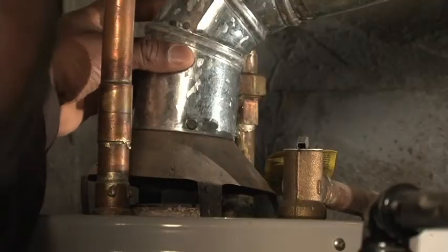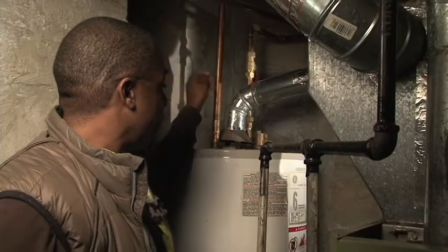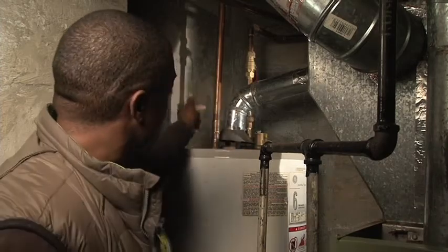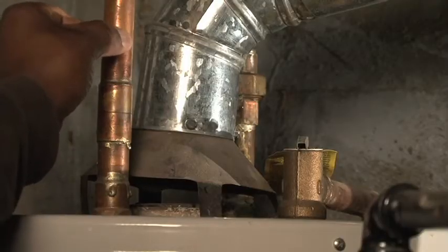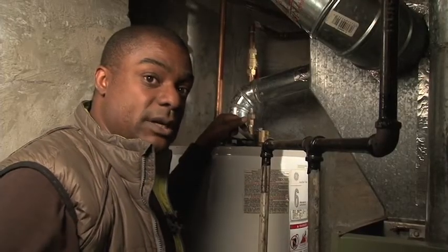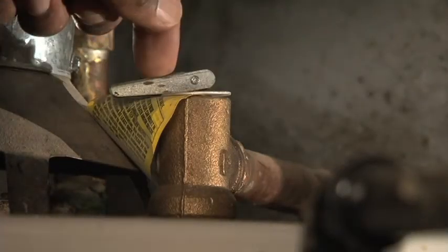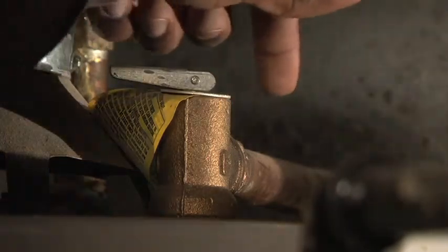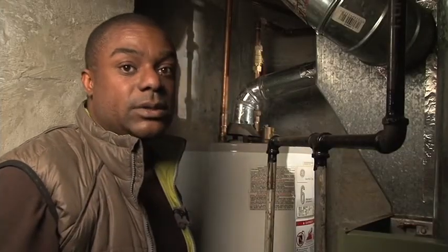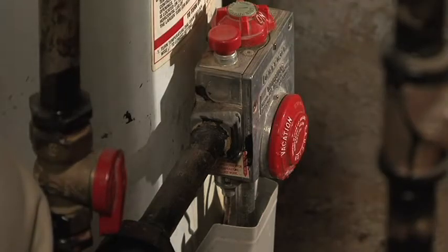When we inspect the top of a water heater, we want to look at how the flue pipe attaches to the draft diverter. Is this the proper draft diverter for this water heater? We also want to take a look at the cold and hot water pipes for corrosion, because corrosion can be evidence of drafting issues with the water heater. We also want to look at the P&T, the pressure and temperature valve, make sure it has piping attached to it and that piping runs all the way down to within 6 inches of the floor. And we want to disable the water heater by turning the temperature valve all the way down to vacation.